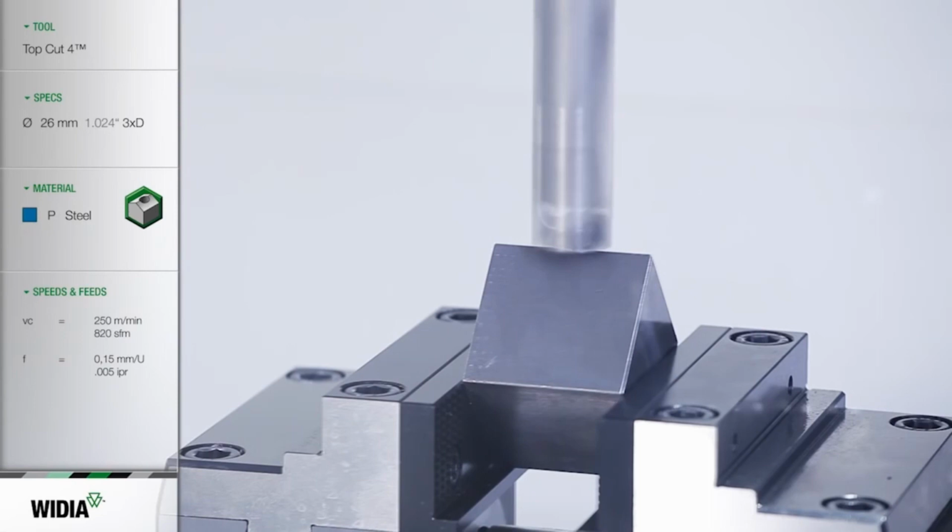If the center part of a solid carbide drill is not cutting, it decentralizes the drill and it can be broken. Here, with this indexable drill, you can see the start of the cutting. Maybe you'll see it in this camera. It is starting to work not in the center, but a little bit to the side of the center. It's much more stable.